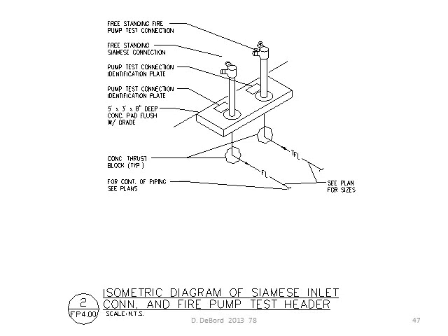It's the fire department connection, where the fire department is pumping water in, and the other one is a freestanding fire pump test connection to test the fire pump, so it's pumping out.